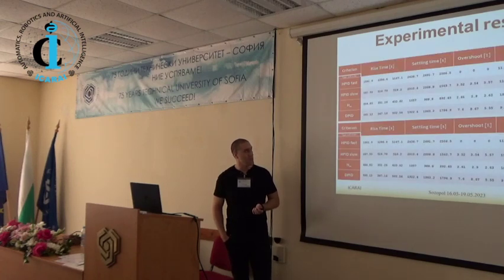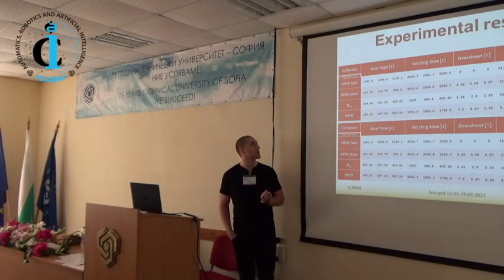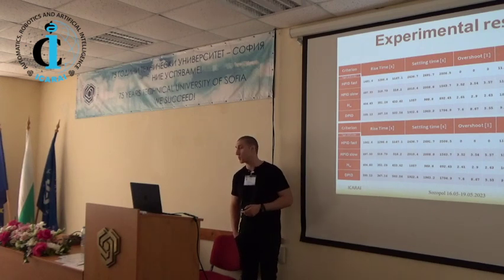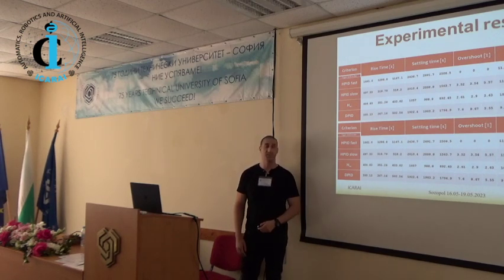At the end again, we crunched some numbers and compiled 2 tables to show some comparison for rise time, settling time, overshoot, and again the square root of the sum of the square of the error and the sum of the square of the control signal.